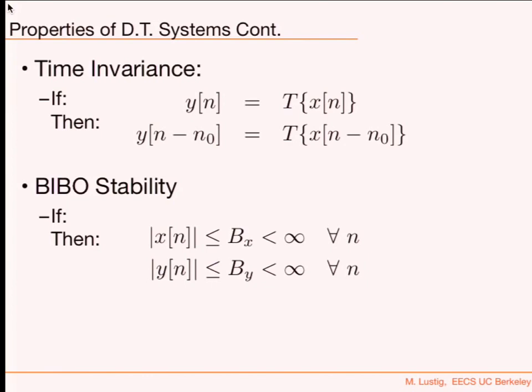For example, your software-defined radios have an oscillator which says on it 28 megahertz. Don't believe it. It's not really 28 megahertz. It varies, up to 5 to 10 parts per million, so it can vary quite a bit. You're going to get a frequency measure that is approximately the frequency, but then you hold it a little bit, and it heats up, and that thing will drift a little bit. But for a short amount of time, it's approximately time invariant. So you've got to be aware of that.